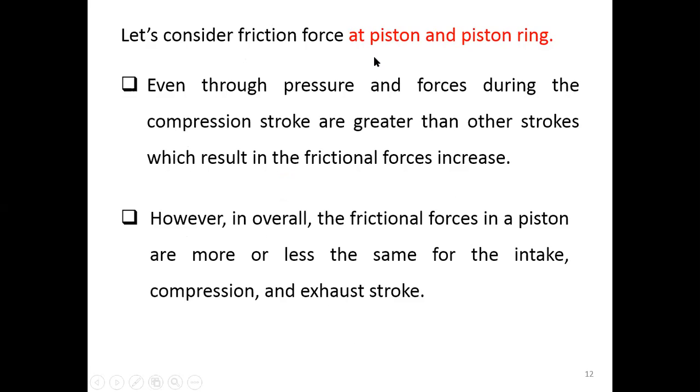What we found is that overall there is not much difference in friction loss or friction force during the intake, compression, or exhaust stroke, even though the pressure and forces during the compression stroke are greater than in the other strokes.